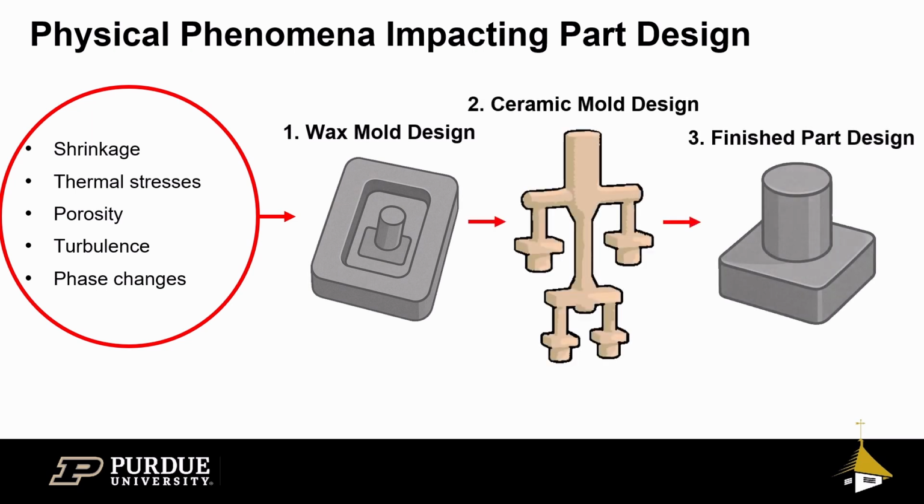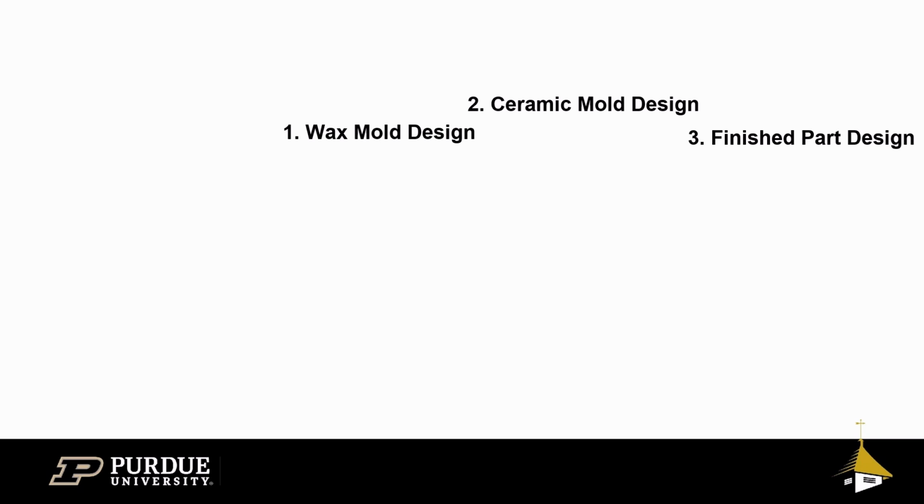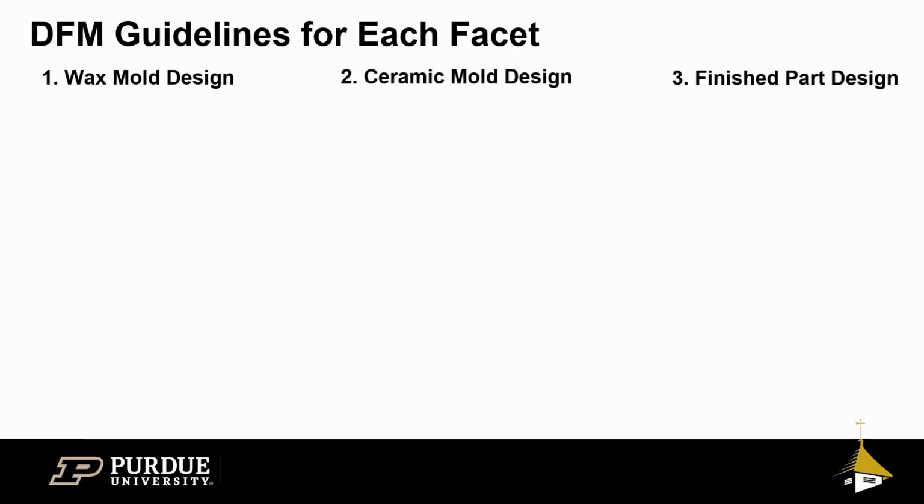Luckily, because the wax mold step is an injection molding process, we can refer to the design best practices for injection molding to assess the guidelines for stage 1 shown here. And we can refer to the casting guidelines to assess stages 2 and 3. So, keeping these relations in mind, let's see how the guidelines for investment casting translates and deviates across these three facets of design.